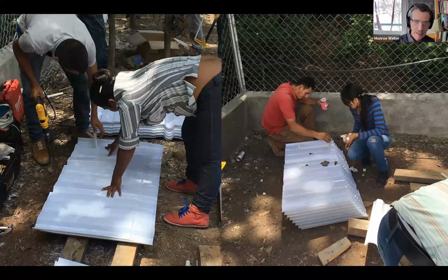Here they're making the plate settlers. The plate settlers are made with polycarbonate sheets that are normally used as a transparent roofing material. The sheets are about 1 millimeter in thickness, and then they're spaced apart using a system of pipes. There's a 1/2 inch PVC pipe that goes the whole way through a bunch of sheets. And then there's a set of 3/4 inch PVC spacers that fit over the 1/2 inch pipe and create the space between the plates.